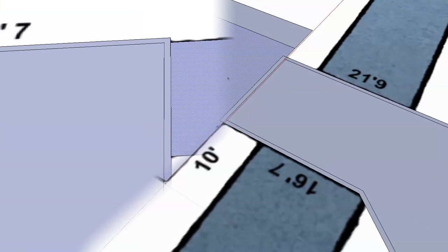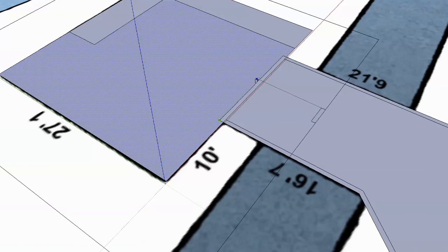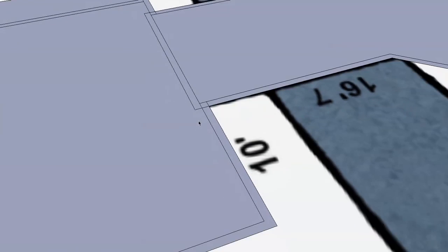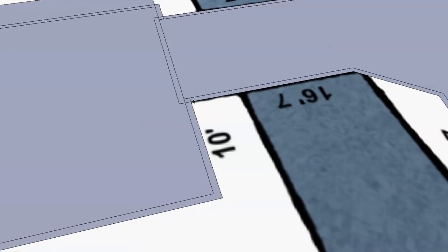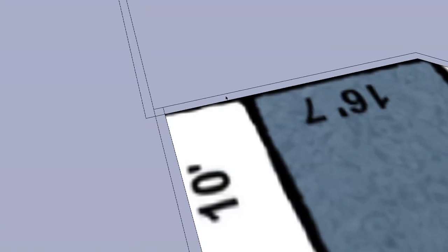It's just a floor. So let's go ahead and offset the master bedroom 6 inches. There we go, and you can see we've got all kinds of weird things that are coming together, but if you just kind of look past all the lines and just see what should be there, you can see if we follow this line, this is the wall coming through here. It should turn the corner here and follow along here, which means we don't want this line or this line, and we got this whole extra wall here that we don't need. So let's go ahead and delete that, and then the same thing over here, get rid of that and that and that. And we don't need this dividing line either. This is looking very good. We've got a couple other little lines here. Don't need those.